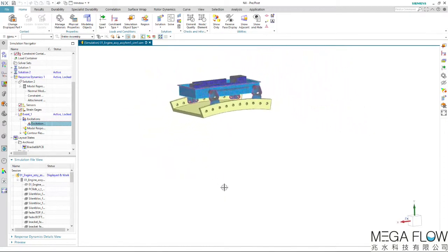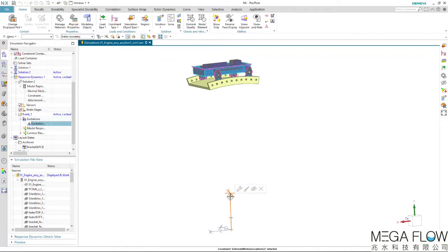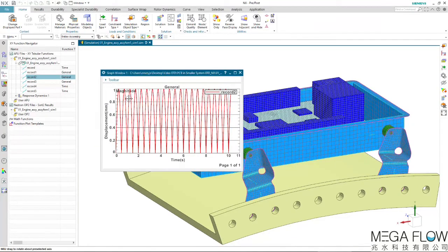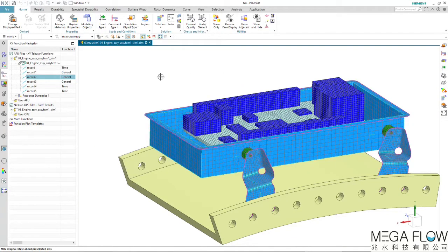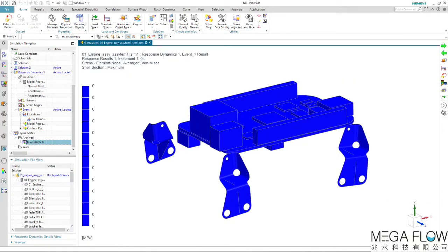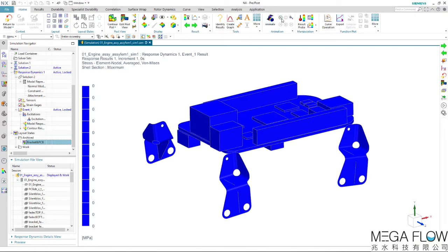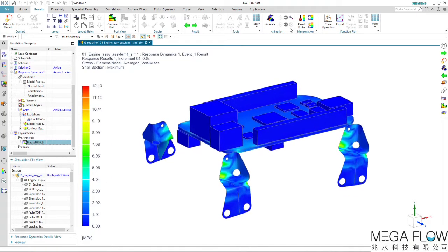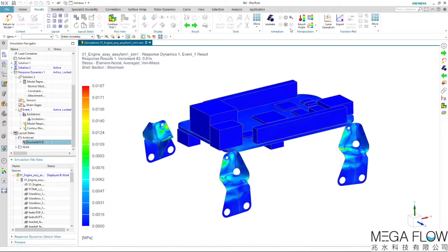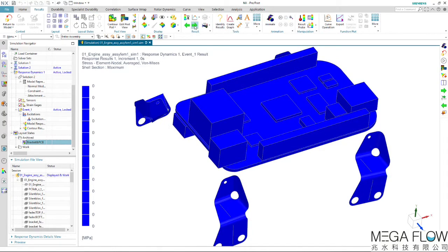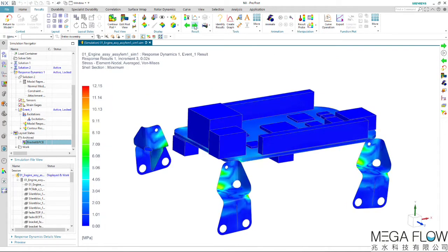A dynamic analysis is conducted with a sinusoidal excitation of 20 Hz from the center. After the solve, we can directly open the results on the same user interface and define post-processing activities. At this stage, we were able to define the mechanical stress on the bracket and the acceleration on electronics components. Transient von Mises stresses are predicted and shown in the support brackets on the PCB. The analysis identifies where the increased stresses are located so that remedial action can be taken.